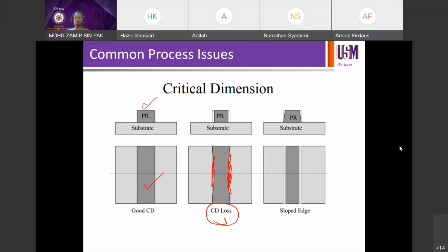Photolithography, and you're talking about front end and back end. Front end, maybe you're in charge of implant and polysilicon, the early steps of the process for MOSFET. If you're in charge of back end in litho, then you're in charge of metal 1, metal 2, VIA 1, VIA 2. We're going to see that when we learn about interconnects. Metal 1 to metal 3 here, metal 4 up to top metal. So there'll be 1 or 2 or 3 engineers in charge.